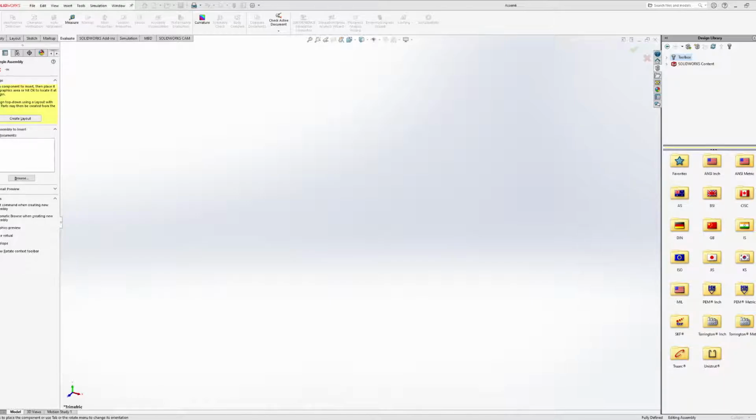So Nick, following along with the in-class assignment, having two issues. I can't seem to get the base and yoke to mate. They keep offsetting slightly. I would recommend in that case to definitely use the align mate.